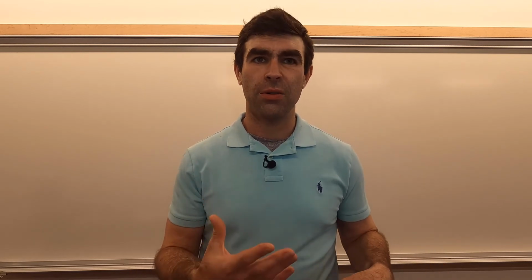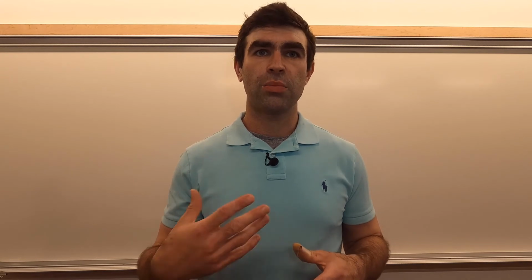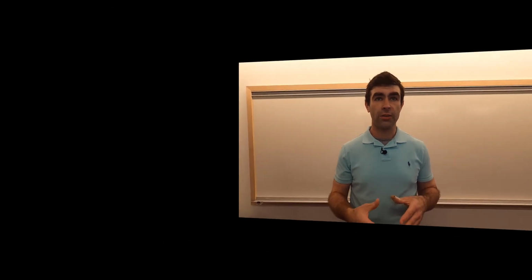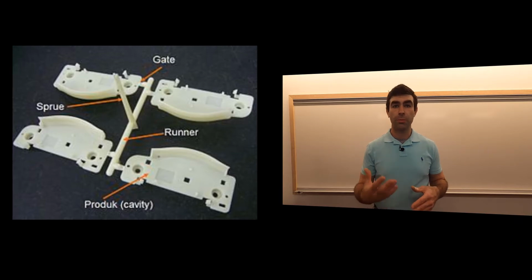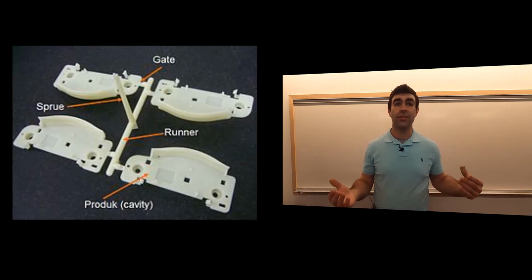One thing to remember with this process is there's always going to be sprues and sometimes runners. Sprues are just a little spout where the plastic has to go to reach the die cavity. So that's going to solidify as well as the part, so that's going to have to be cut off the part. The runners are little connections. Say you have enough space to put several parts side by side. You have to have a connection for the plastic to flow. That's the runner. So those have to be snipped sometimes.